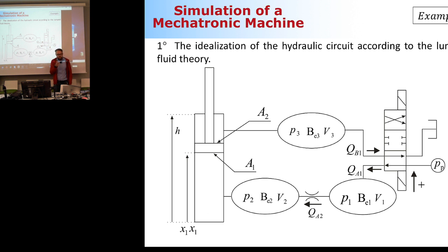This is a typical mistake that people make when creating the hydraulic equations. Typically they consider the flow rate directions inconsistently, so you cannot change them any longer. Like here, the flow rate comes to this volume 1. This is the one that is coming, and this is the one that is leaving. This is how I define whether these are positive or minus sign. It's very, very important.